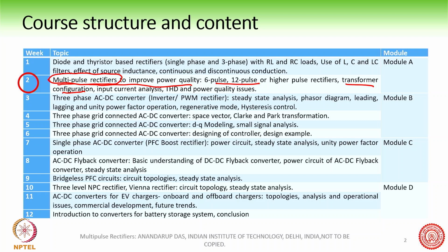The reason why we are studying this is because, as I told you repeatedly, as part of the rectifier study one must remember the input side, the input power quality, also. This solution based on multipulse rectifiers is one of the most economical solutions. It's cheap and easy to fabricate, and this technology based on rectifier and transformer is a very well established technology. That is why in many applications, industrial drives for example, we repeatedly see the use of such multipulse high power converters or high power rectifiers.